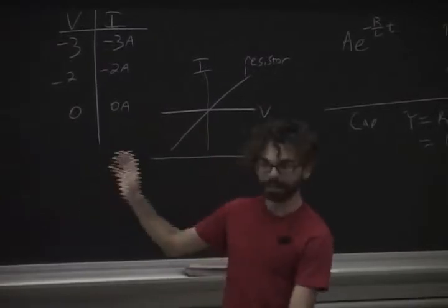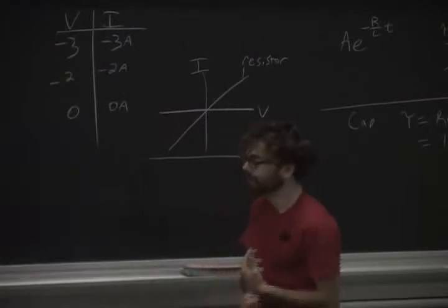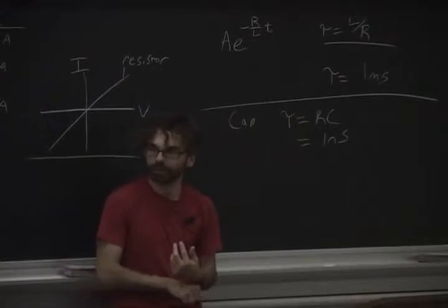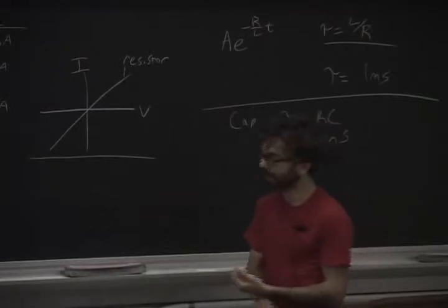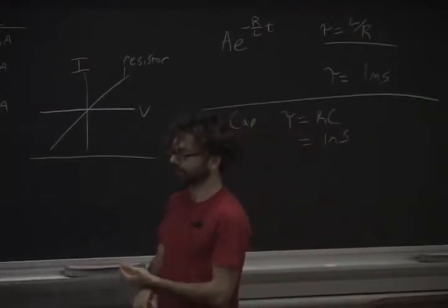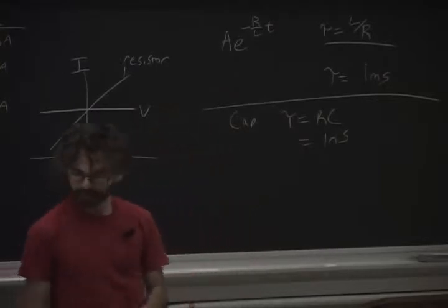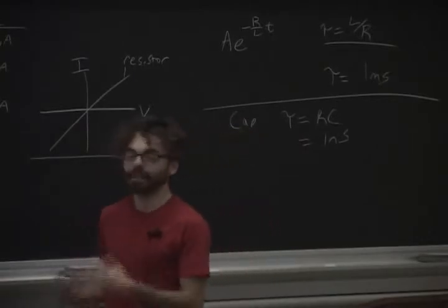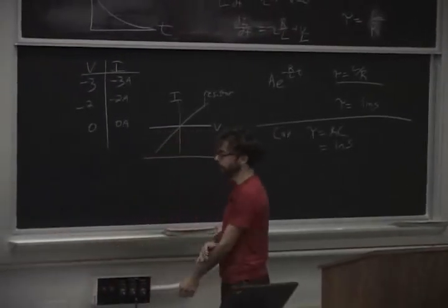Sorry for the confusion on the inductor there. Has everybody got this? Does it make sense? Now, if you applied a current source to a capacitor, what would the voltage do? It would just grow, grow, and grow, right? If you had access to some kind of current source that could keep driving current forever, you would be able to, in very short order, pump an insane amount of energy into a capacitor. Luckily for us, current sources are not ideal, and if you try to provide that much voltage or power out of them, they'll break down. They'll stop acting like current sources.